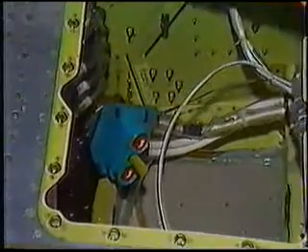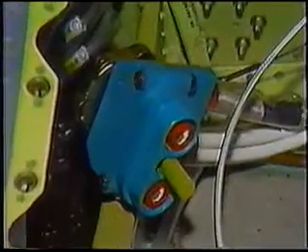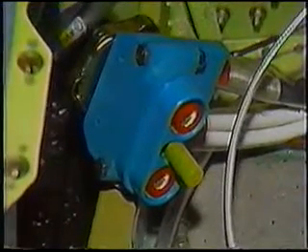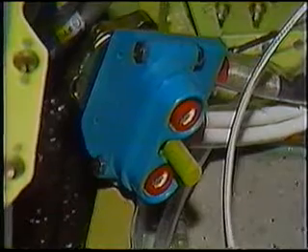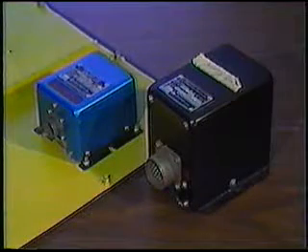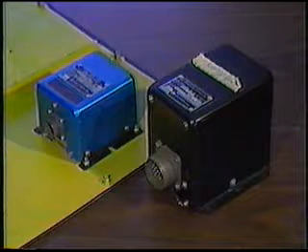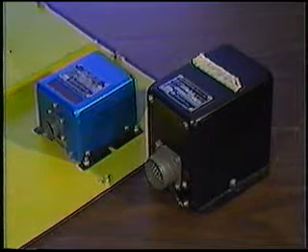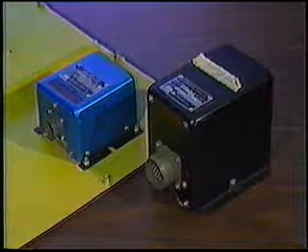Connectors are another source of electrical problems. The battery connectors are easily overlooked in troubleshooting efforts. Again, any sign of overheating or arcing needs further investigation. The fault detection systems of both the battery and the generator circuits can be sources of aggravation. Much of this trouble can be attributed to interference from other circuits on the aircraft, rather than actual faults.